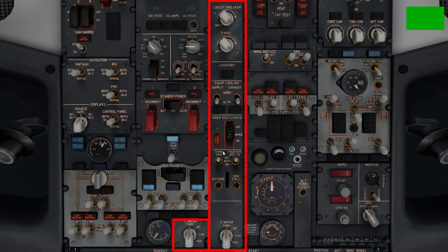Underneath this is an open black cover which controls the emergency exit light strips that run along the cabin floors, as well as the emergency exit signs at the top of the doors on the aircraft. In a cold and dark state, these are normally set to the off position to conserve battery power. However, flipping the cover down automatically arms these lights in the unlikely event of an evacuation or an emergency.